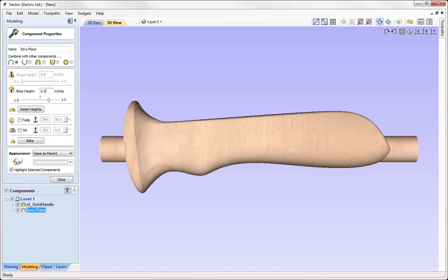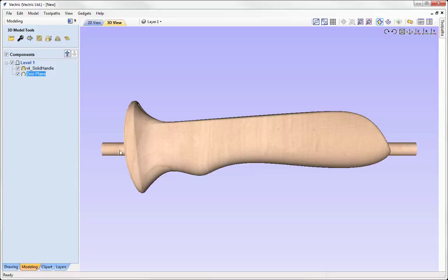Okay, so that seems a little bit too excessive, so what I might do is look at shrinking that to 1/4 inch in there, like so. Okay, so that's not too bad, and then we can just simply close that out, and I've got a 1/2 inch diameter tab at the end, and this will provide us with some material to cut down to when we create the toolpaths, and it won't end up cutting the parts out of our piece of stock.